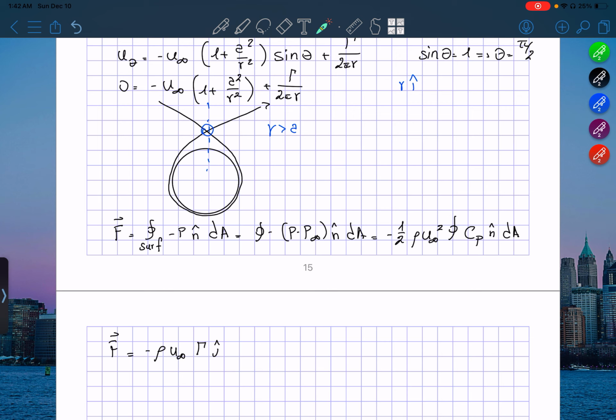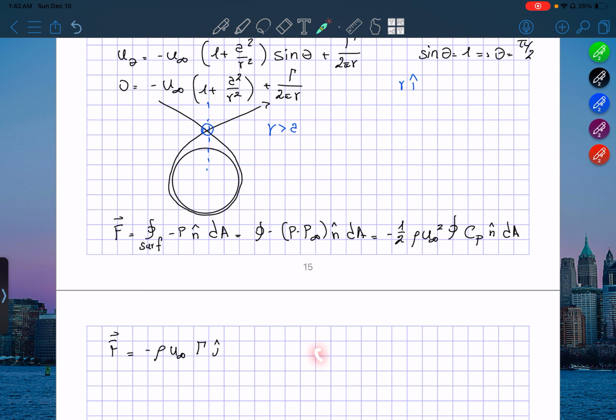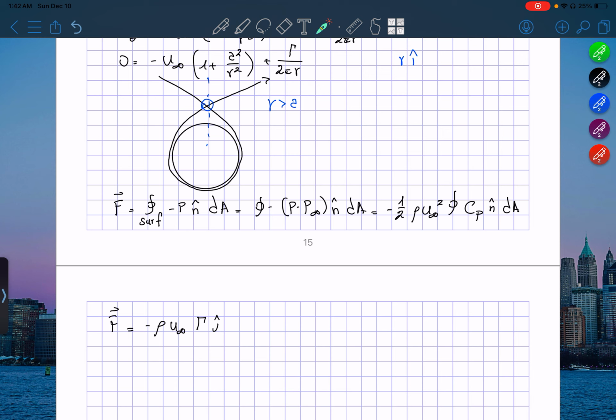This is actually being done in some boats that have a rotating cylinder, and if they rotate fast enough, they can actually create a force that pushes the boat forward or backward depending on their direction and on the flow. In fact, the higher flow will make it have a higher force, and a higher circulation, of course, will make it go higher.